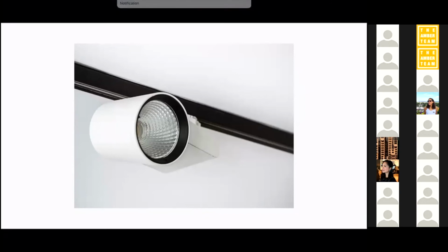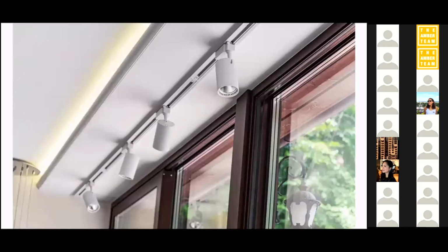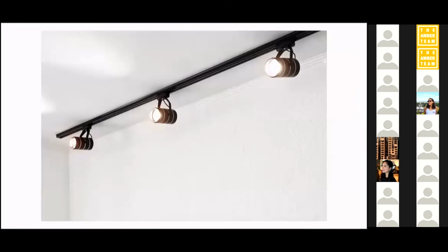So track lighting, the beauty of track lighting is you have flexibility to loosen this and slide it down to here. But in order to give us that flexibility, on the inside of this, if we were to tuck our fingers in here, we would be the conductor, we would be the short connecting the hot to the neutral. We want the electrons to go through the lamp and then back again, but we don't want our fingers to be the thing that's arcing the electrons across between the hot and the neutral. So what we're going to do for track lighting is use low voltage.